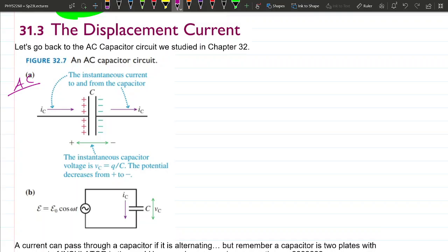Where you have some alternating current. What's happening is that as the voltage on this side goes up, you get some positive charge here. So if I plot voltage versus time here, it goes up and down. When the voltage is positive here, it's going to make some positive charge here. When the voltage is negative here, it's going to flip this. It's just flipping back and forth across the capacitor. And I've been telling you that that allows you to transfer current over the capacitor. Remember, on a DC circuit, the current cannot hop over that capacitor. Only in an AC circuit can you have this oscillation.